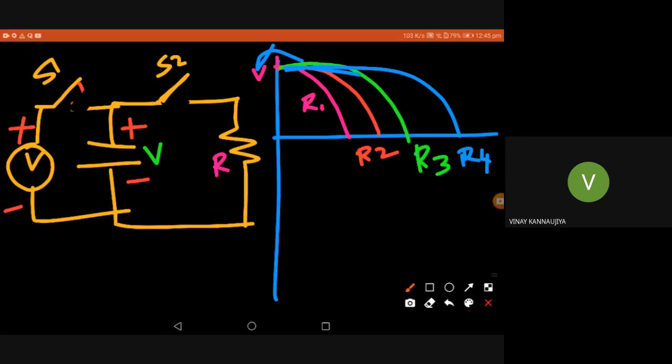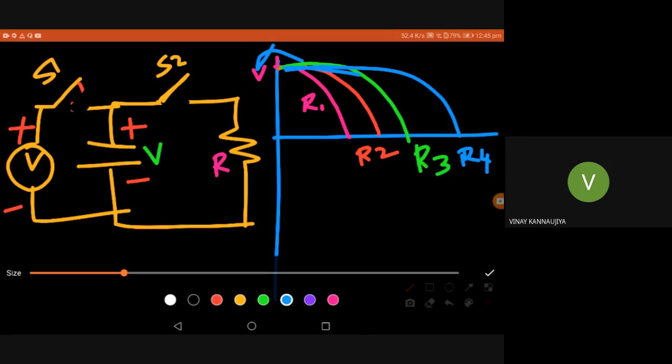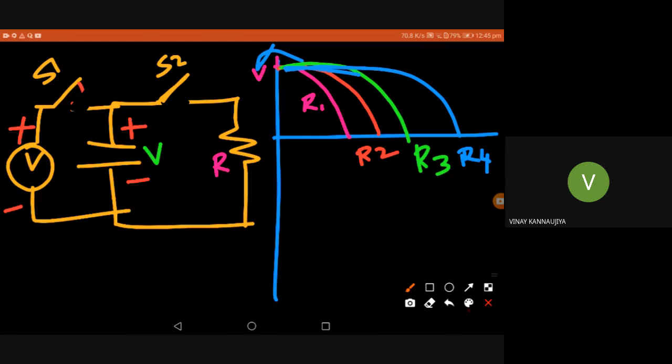So what does it mean? According to the value of my resistance, if I take a very small resistance, the capacitor may discharge very easily. So what is the idea? It is the designer who chooses the values of R and C, and that decides the waveform. If I keep a very large R, it takes a long time to discharge. So practically I get a very big curve. Still, it is impossible to keep the charge for infinite time, but I can reduce the discharge of a capacitor.